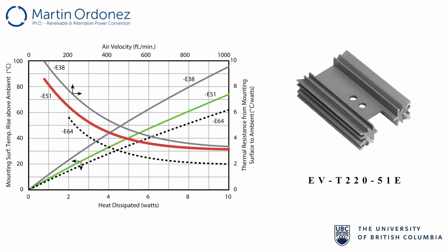One curve, which is from the top left side to the bottom right side, shown in red, and another one from bottom left side to top right side, shown in green. The first one is for the forced cooling system, which is when a fan is connected to the heatsink, and another one is for the natural cooling system, when there is no fan connected to the heatsink.